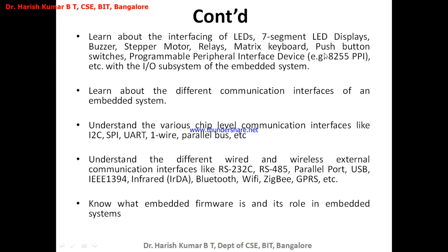The push button switch is one single button which is used to perform multiple operations. Say for example, the garage door opener. I want to open the door, I want to close the door. I don't require two push button switches for performing these operations. I can manage everything using one push button switch. And this push button switch operates by examining the current state of the machine. Say for example, if I consider the garage door opener as the machine, and I have one push button switch. Now if currently the garage door is closed, and if I push this button, the door will start opening, and when the door is in the open state, and if I press the same button again, it will start closing. So this push button understands what is the current state of the door, and then behaves accordingly. It takes the system to the next state based on its current state.